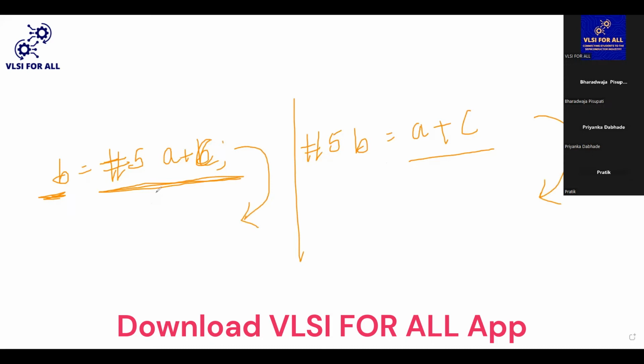But whenever we are using some particular delays, a strange thing appears here. Whenever we are using hash five here, what will happen is, first it should update the values which are there on the RHS side. So here, whatever the values of A and C are there, those values will get updated, and all those values will be assigned to the variable B after the 5 nanoseconds, after this particular delay.